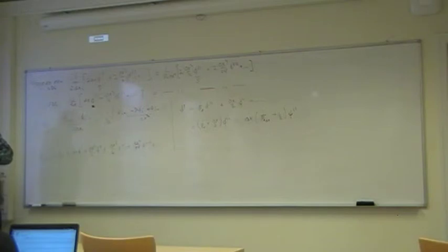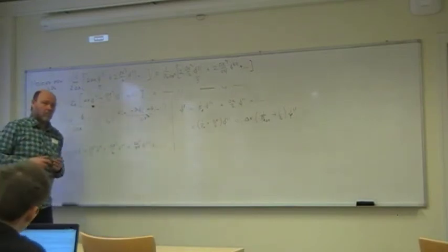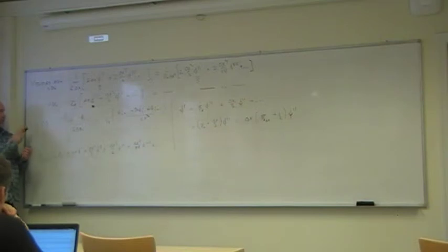Questions to this one? So is it better to use CDS? Absolutely. So the central scheme is much more accurate, and also I would say it's an advantage that it will blow up if you do something stupid. The upwind scheme is stable no matter what you do.